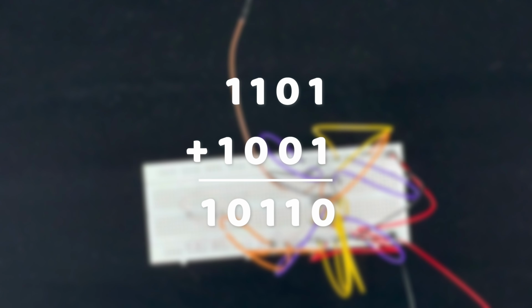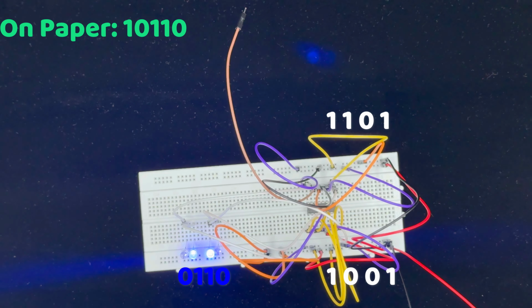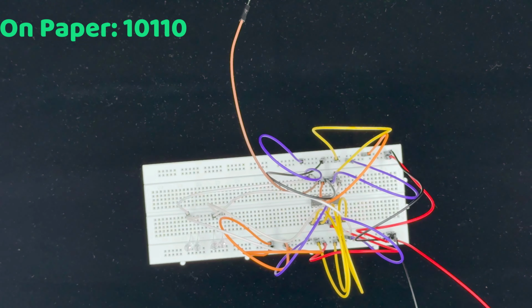Now let's add 1101 and 1001. On paper, the result is 10110, 5 bits. Let's see what our adder thinks though. Unfortunately, it thinks the result is 0110, which is the same result for the numbers we added earlier. So this is a big discrepancy which makes our adder totally inaccurate.